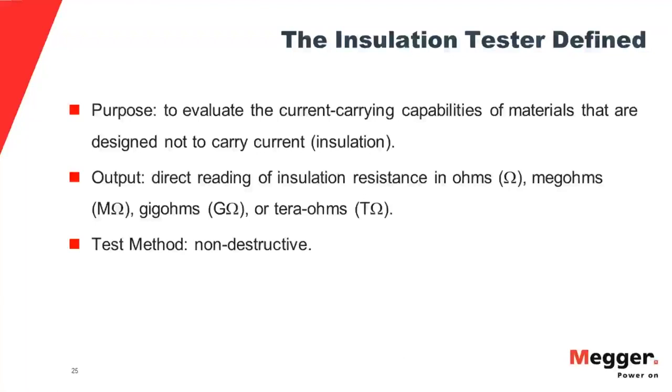Consequently, the testers have a lot of voltage but very little power, and they are non-destructive, and they're non-injurious at the same time. They can sting you a little bit, but even a 15 kV tester can't actually injure the operator himself. But at the same time, the test item can be dangerous, and we'll come back and talk about that. So these testers are non-destructive.